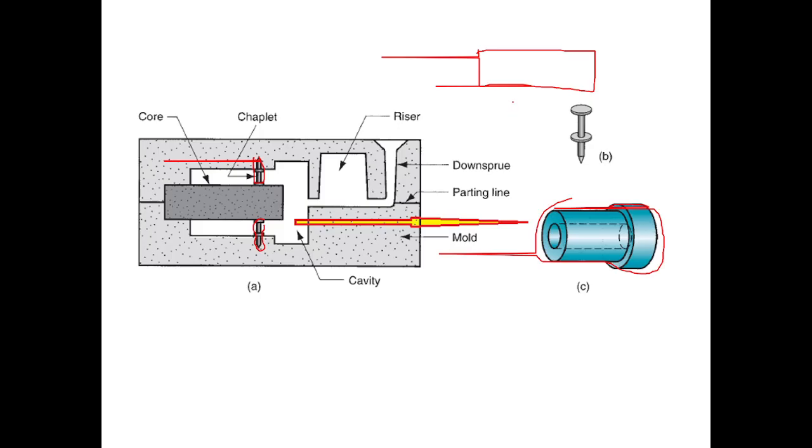And then draw the free body diagram. This end of the core has been immersed into the mold, so it is like a fixed connection. The sand particles of the mold apply a force system.